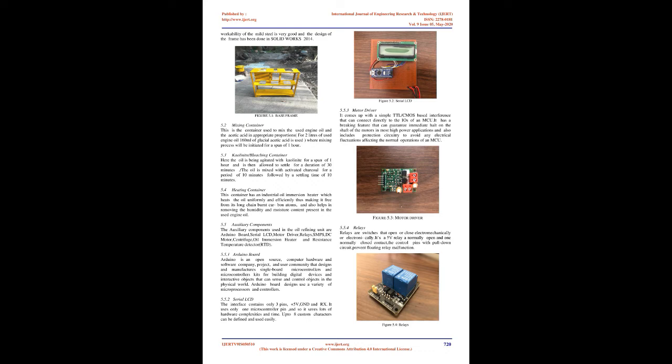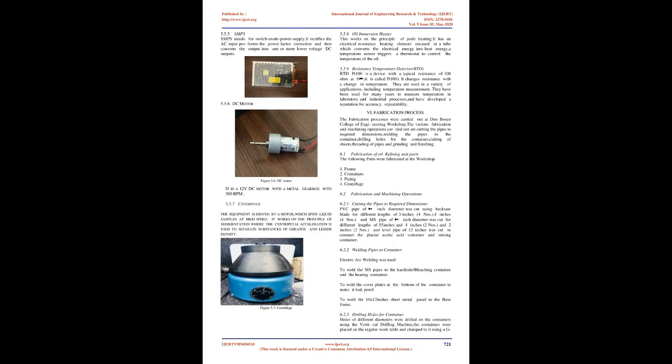It comes with a simple TTL/CMOS based interface that can connect directly to the IOs of an MCU. It has a braking feature that can guarantee immediate halt of the motor shafts in most high power applications, and also includes protection circuitry to avoid any electrical fluctuations affecting the normal operation of an MCU. Figure 5.3, Motor driver.